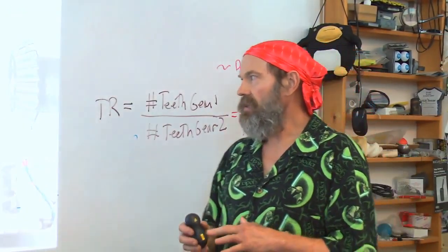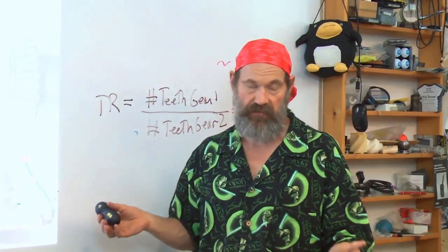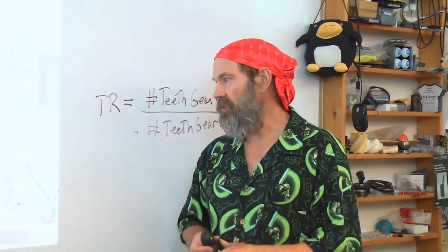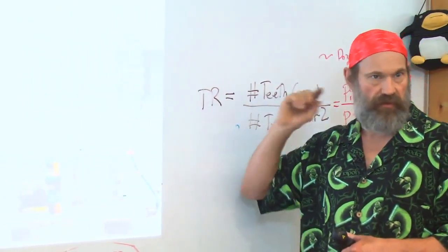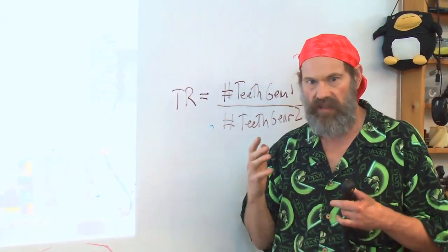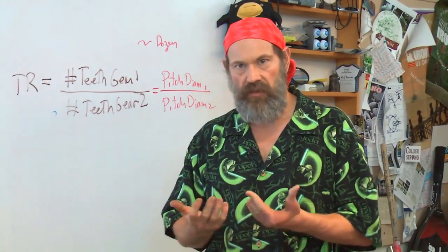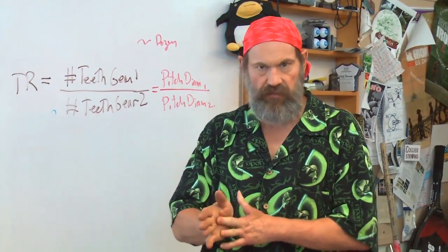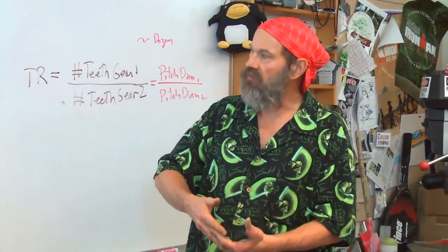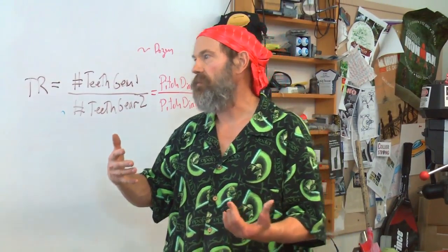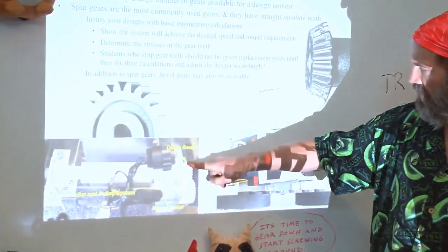When you start looking at taking gears and using them in your robot designs, for example, if you're designing for a robot contest, you got to remember that you may be given modular gears, but you got to mount them correctly. You have to be very careful about where the hub is and the gear tooth separation forces. Remember, they can be substantial, and if the gear teeth are mounted so they're on cantilevered shafts, when you start pointing a lot of torque in them, the gear tooth separation forces can pry the shafts apart and the gears can skip.